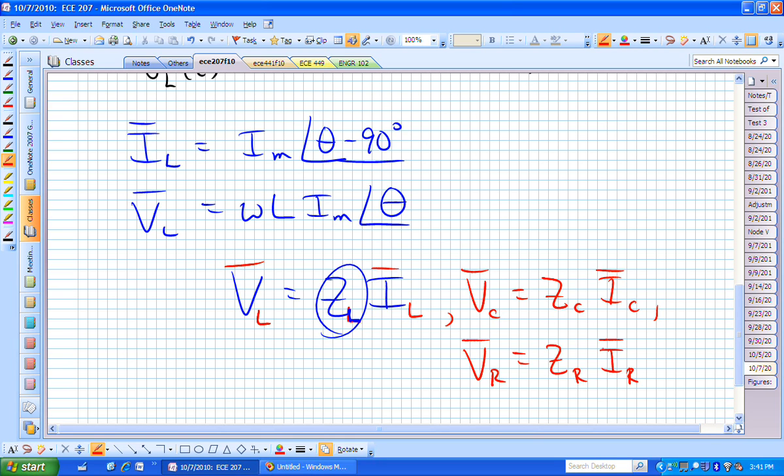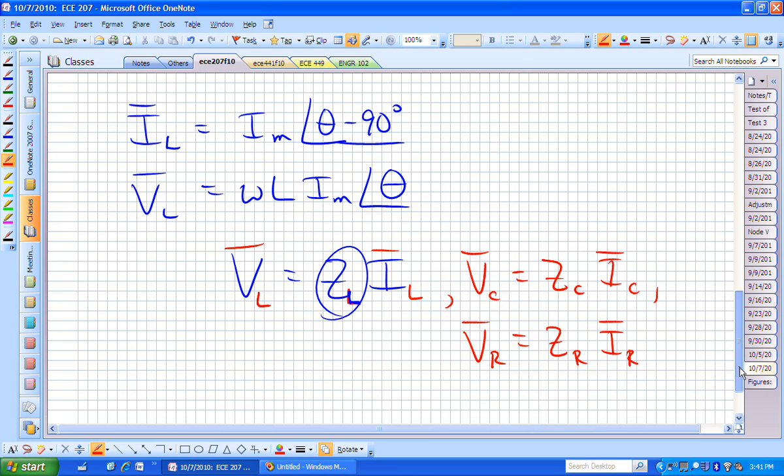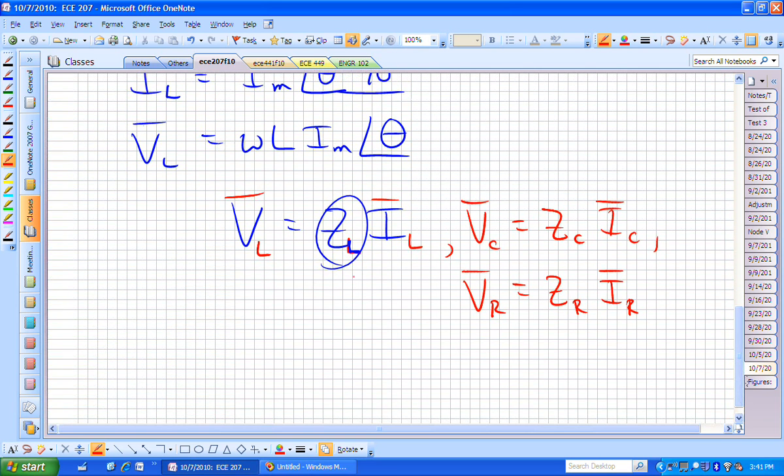and we also want the relationship for a resistor. We're trying to now define or identify these different Z's, and hopefully we will find that those Z's are different depending on whether we're dealing with an inductor, a capacitor, or a resistor. I think you can anticipate that Z sub R is actually just going to be the R, because a resistor does not depend on frequency. V is equal to Ri all the time. It's not a differential relationship.